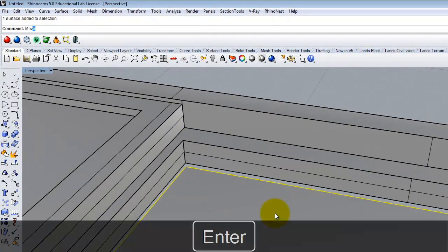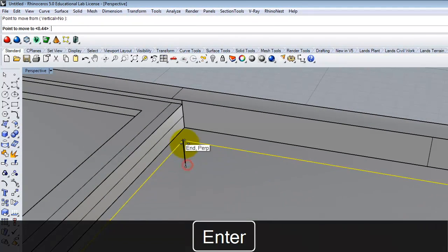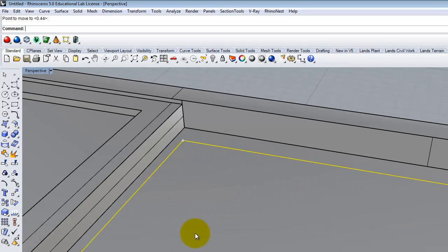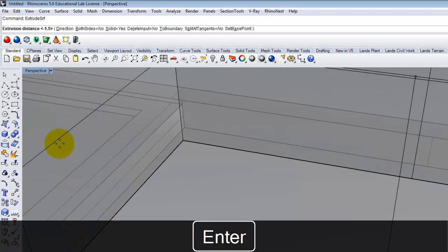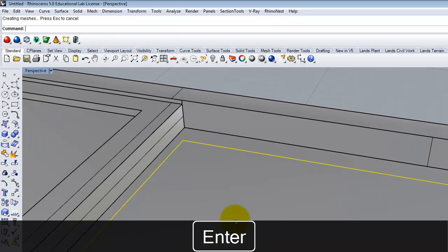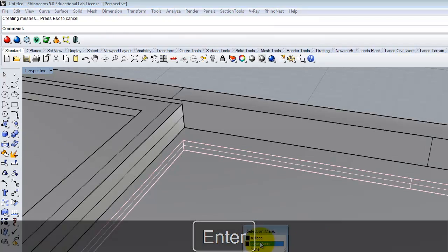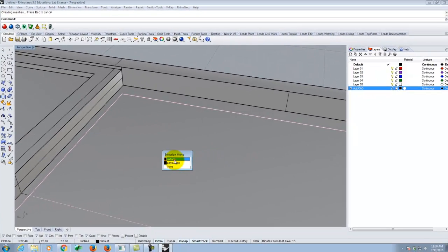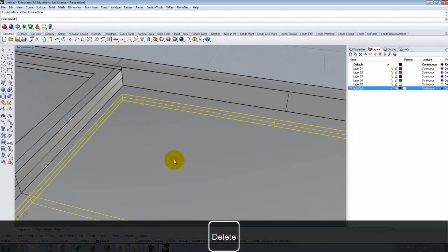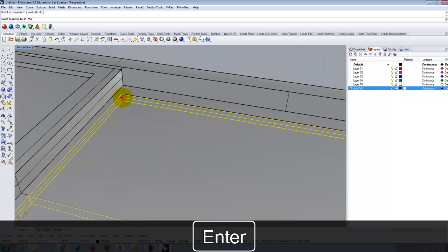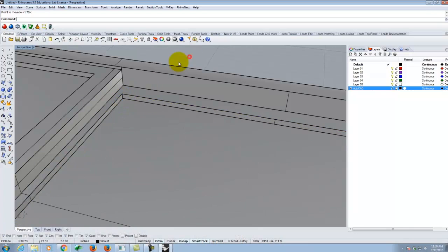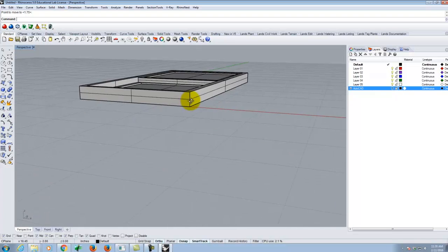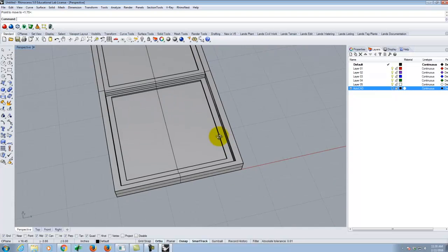Okay, so let's go ahead and move this up again. There. And then I'm going to extrude this. So same thing, extrude surface, negative 5/8. And then I have to move. See, there I am. Because I turned it off, I get doubles. There. We'll go to move, from the midpoint down to the midpoint. And now I've essentially created the bulk of what that window should look like.